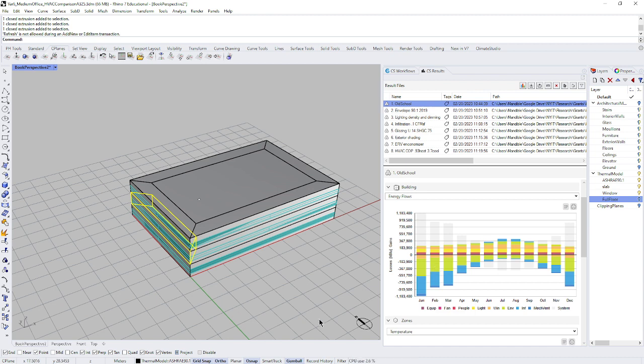It's an iterative total heat loss or total energy efficiency simulation. So that's what, at least in my sections, I focused on last semester, because that's what we would use to design the building. Then once we get to needing to understand the HVAC system, that's when we need the peak heat loading, because we need to understand the most heating or cooling we're going to need at any moment, because that's going to determine the size of the HVAC system.